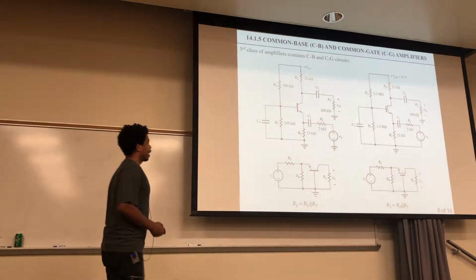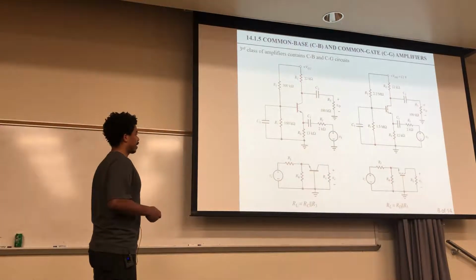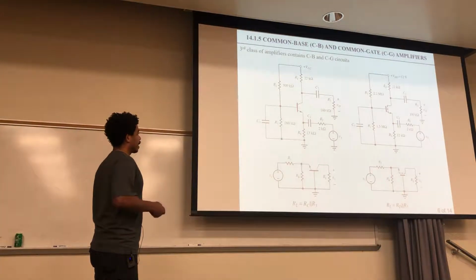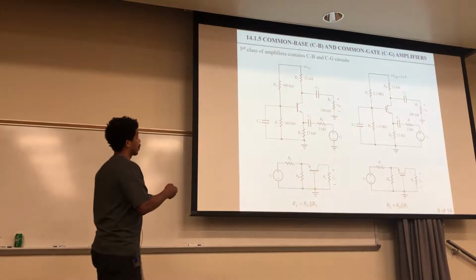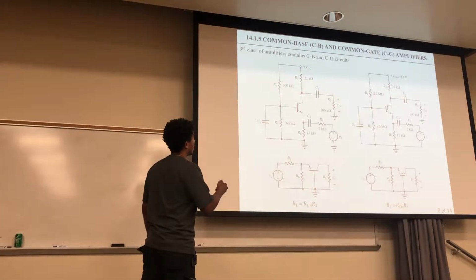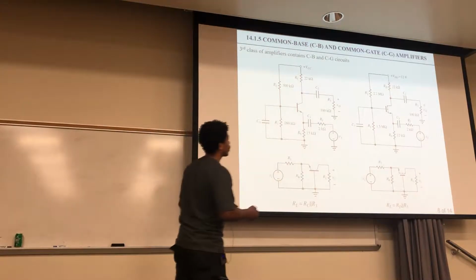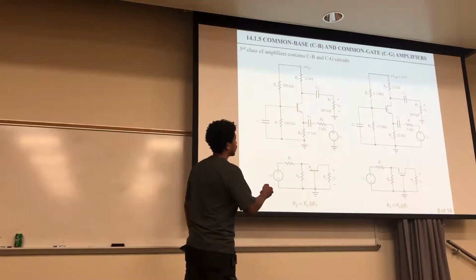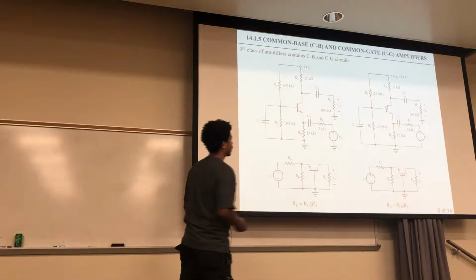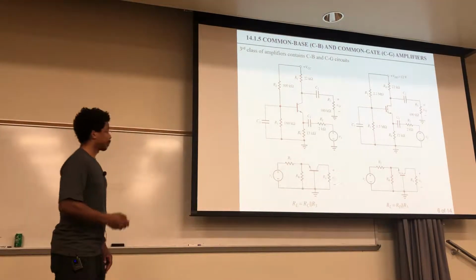What happens is that this load, R3 in parallel with RC up here, becomes ground. So here's your starting node, and then they both go to ground right there. So that is in parallel with that, and that gets short-circuited. Over here it's very similar, where you have this RD in parallel with R3, where that is grounded and this becomes short-circuited. So that's where those things come from.